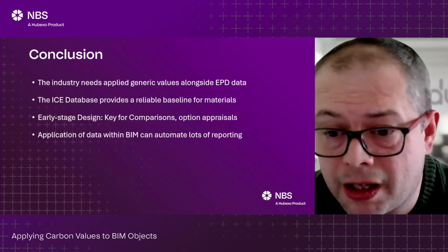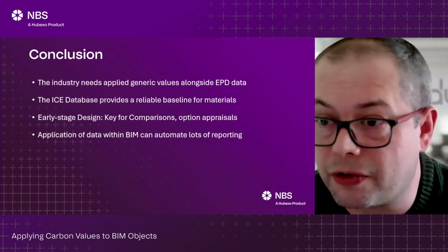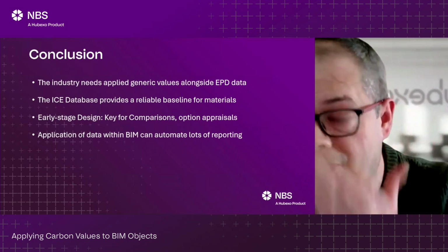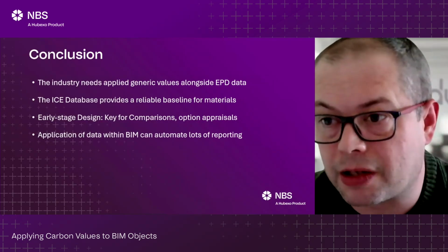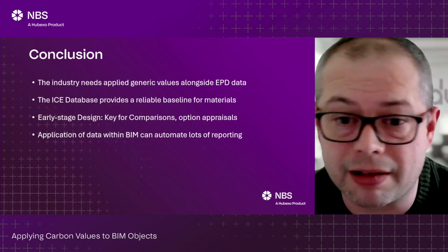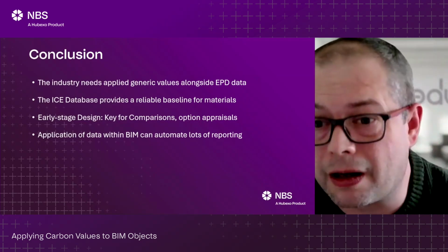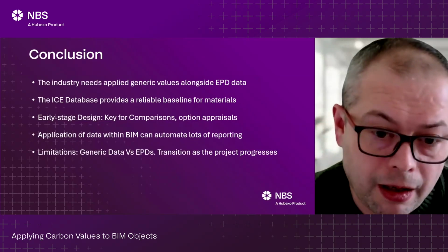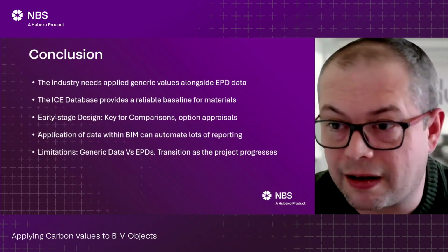Application of data within BIM can automate lots of reporting. There will be a caveat in terms of not everything always being modelled. An architectural model might not have the foundations model, for example, so you will need to combine things like the structural model, the architectural model, the MEP model, for example, if you wanted to do that full calculation. But in terms of early stage, particularly if you're looking at building fabric, it's a real good place to actually start to do this.